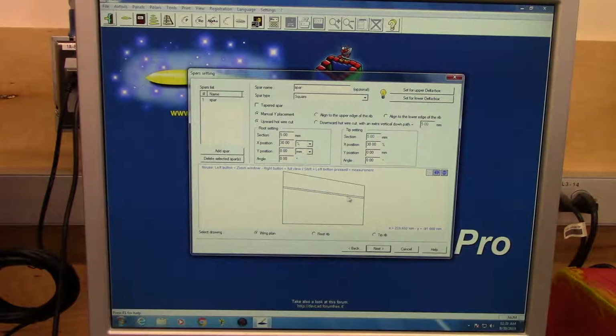The spar I'm going to create, I want to go through the entire tail so that it can help support both together, and I don't get that weakest point of contact here at my root. And so I want this spar to actually be flush. Furthermore, they're flat between both sides.